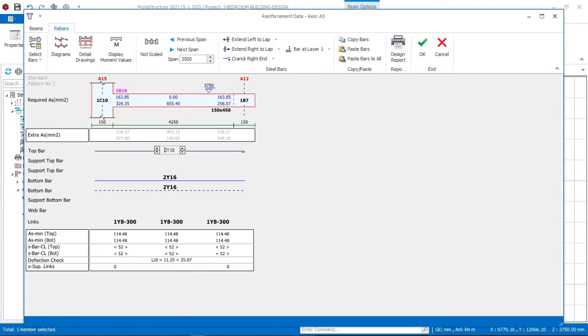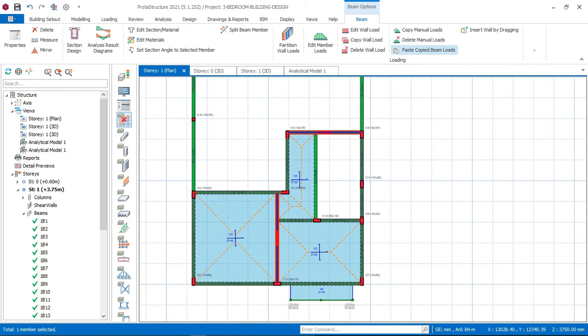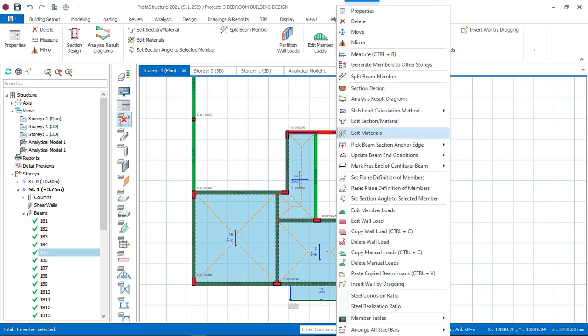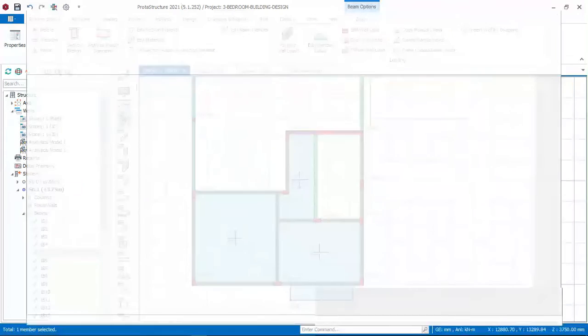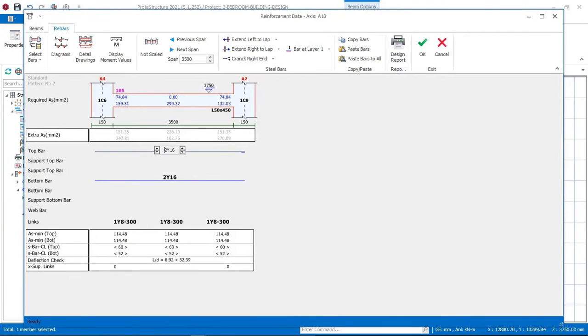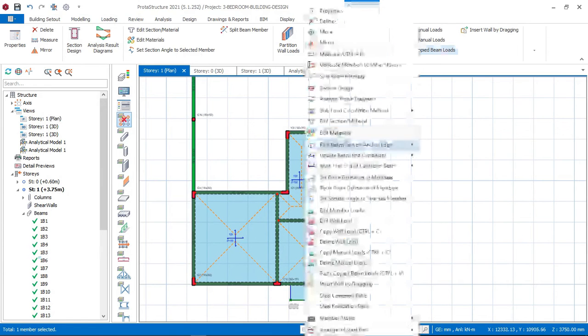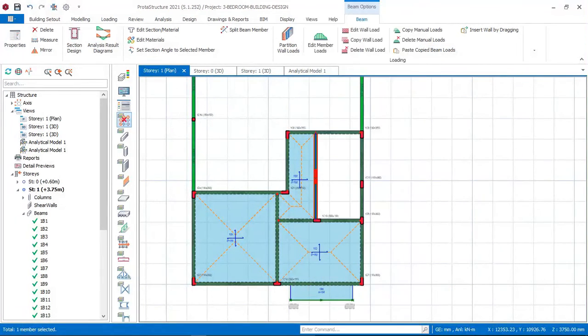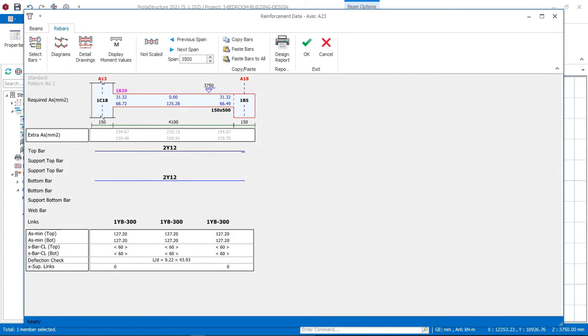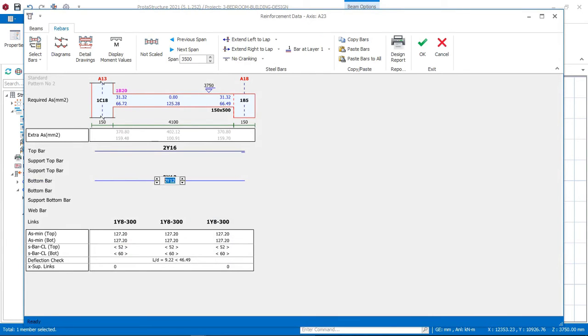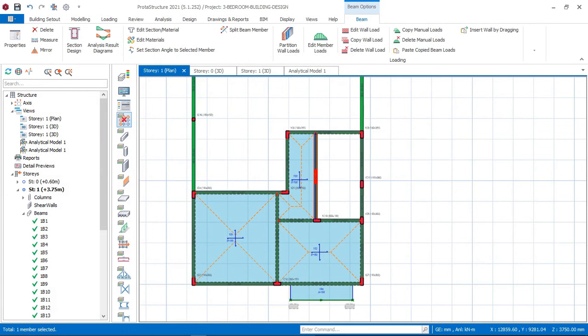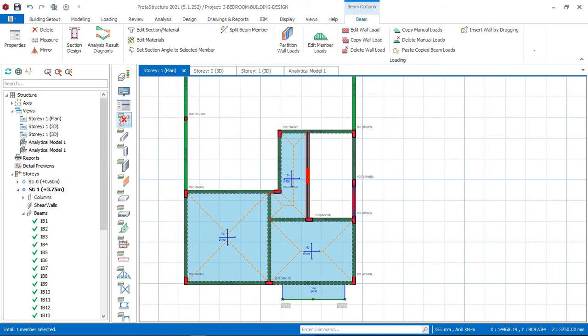So when I click on what? Okay, that's okay, and do the same thing here. I click here and say properties, section design, and click on this, increase that, and this is okay, 2 up, 2 down, that's okay, and do this also. And then I'll check this also right now. I click here and then click on section design and check the reinforcement there, decrease to 16 and also to 16, and then okay. And then I will now go here and check this particular one right now.